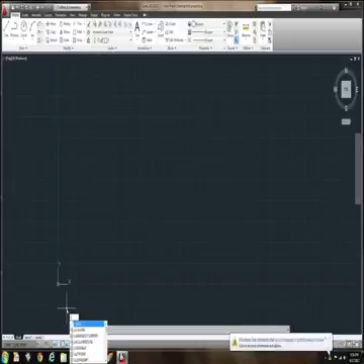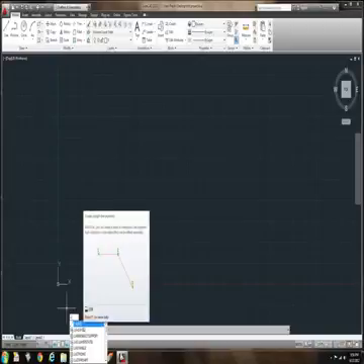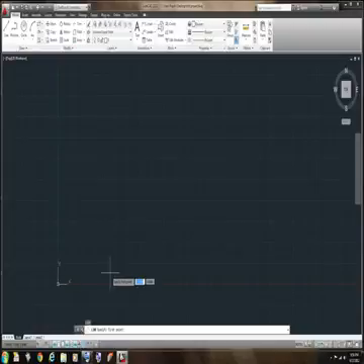As you can see, AutoCAD now is giving me a set of options by default, and this is new for AutoCAD 2013. As you can see, I have here the L, and AutoCAD is giving me all that is related to L: L for line, LA for layer, large object support, LAS for layer state, and so on and so forth. So a set of options. In my case, I type L and hit enter, and the same command line.